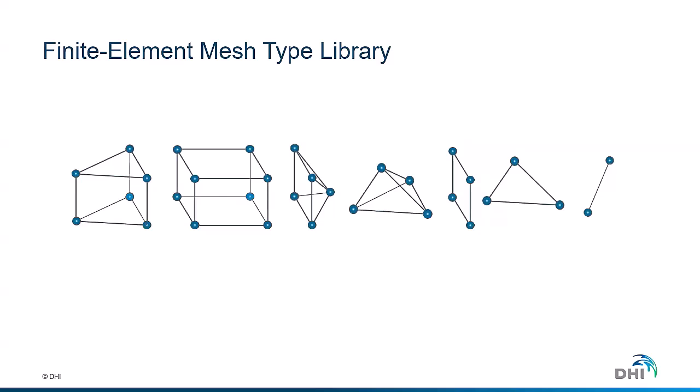As you know, FEFLOW is a finite element software, and back in 2015 we introduced what we call 3D and structured meshes. Simply put, this means that we have extended our library of finite element mesh types, which allows us to create numerical models with a high level of discretization and also to honor the different and complex geometrical constraints which could come from geological software, but also from geotechnical infrastructures like wells, inclined wells, underground tunnels, pipes, mining infrastructures, mining plants, etc.